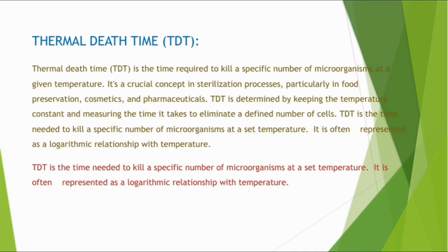It's not just about how hot it is, but how long you need to maintain that temperature to effectively kill the microorganisms. You can think of TDT as a way to quantify the lethality of heat in sterilization. Interestingly, it's often represented using a logarithmic relationship with temperature, meaning that small changes in temperature can significantly affect the time needed to kill microorganisms.